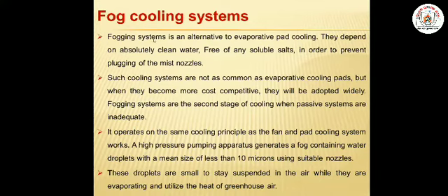Fogging systems, or fogger systems, are an alternative to the evaporative cooling pad. They depend on absolutely clean water free of any soluble salts in order to prevent clogging of the mist nozzles. Such cooling systems are not as common as evaporative cooling pads, but when they become more cost competitive, they will be adopted widely.